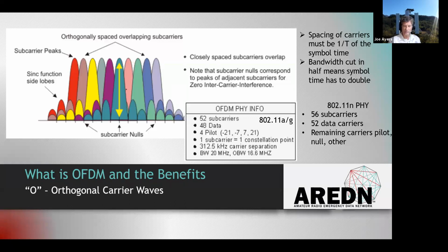They're designed to optimize the signal so that it minimizes interference with adjacent 802.11 signals, and minimizes inter-symbol interference, both across time when transmitting the next symbol, and inter-carrier wave interference. So it's a lot of smarts. We could take a whole session and dive into how all of these subcarriers are modulated to optimize it.